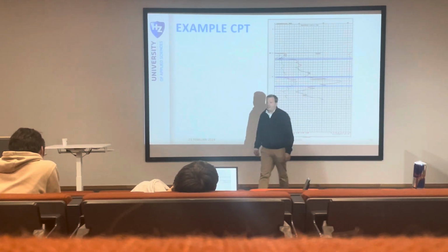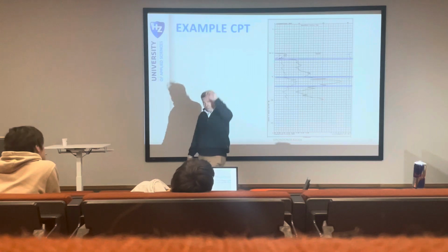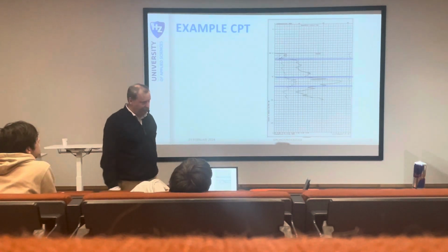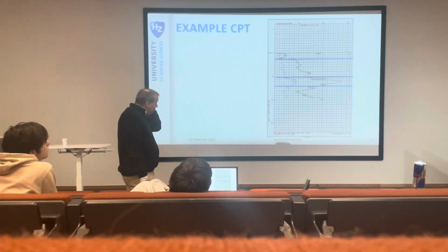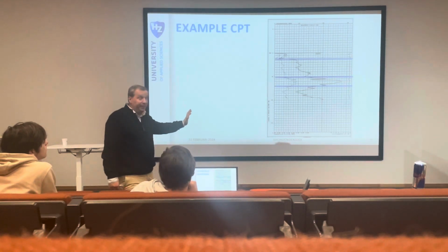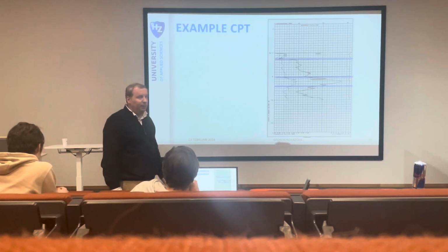If you have piles, you have to drill them so deep that you come to that sand layer, and then they are well attached. On the other side, you can have peat. When it's very weak, it's peat soil.